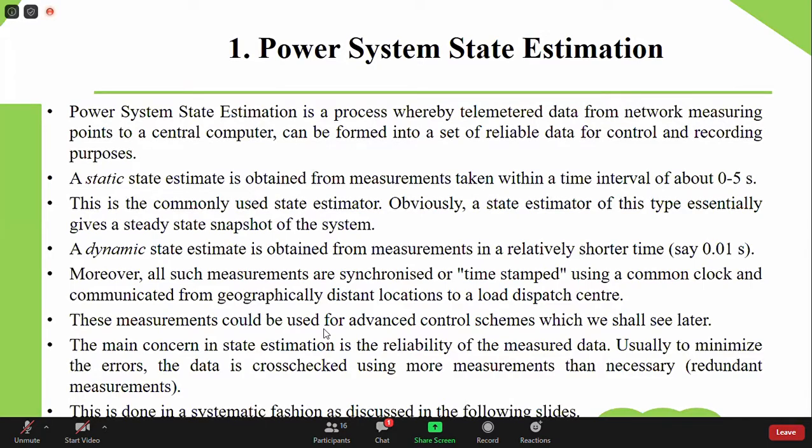So if somebody asks what you understand by power system state estimation, it is just a process where you collect data from the network measuring points. For example, you want generation data, so you collect it from Chuka, Tala, Kurichu and others in Bhutan, and send it to the central computer, which in Bhutan is BPSO.